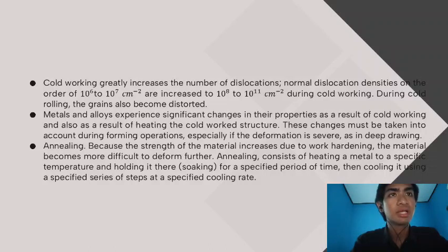Recovery and recrystallization are two distinctly different processes. At a constant temperature, recovery starts rapidly and then decreases with time. On the other hand, recrystallization, which is a nucleation and growth process, starts slowly and then builds up to a maximum rate before rapidly leveling off.